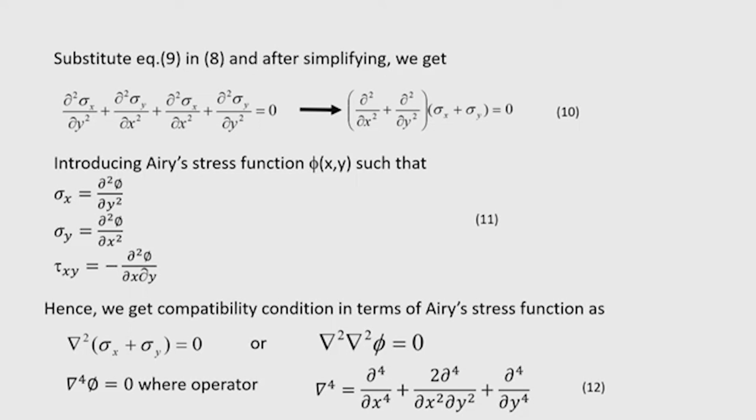Because when we solve the equation of a plate simultaneously subjected to in-plane forces and transverse loading, if we introduce this stress function, it will be convenient. Earlier we obtained the equilibrium equations: ∂N_x/∂x plus ∂N_xy/∂y equal to 0, and another equation ∂N_y/∂y plus ∂N_xy/∂x equal to 0.